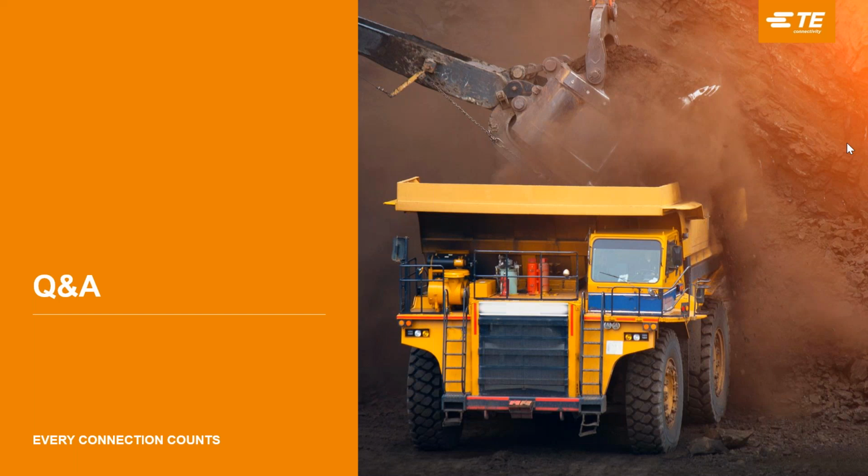So Enet Steel Plus is based on the MCON terminal system. There are hand tools available for that type of connection, and there's a very detailed application spec for termination. It's certainly the choice of the manufacturer, right? You have to have a technician who understands what they're doing and can follow the application spec, and has some level of training in the proper crimping and stripping of wire, and also a little bit of understanding that this is a twisted pair cable and there are certain application requirements that have to be maintained, but nothing that is not easily learned, let's say that.